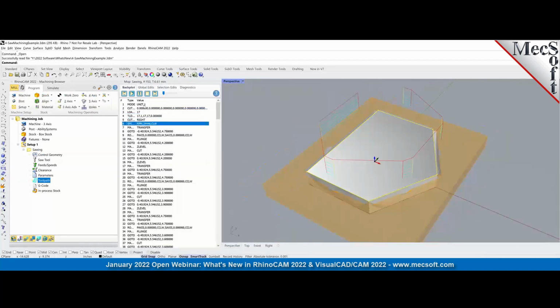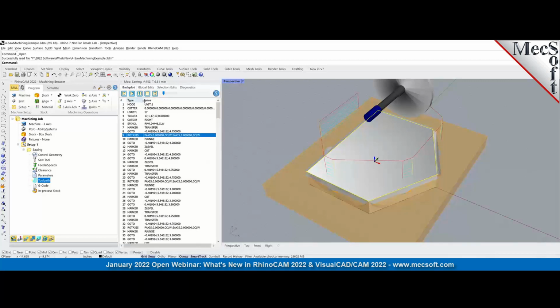This is our toolpath viewer. As it comes in here, you see a rotate axis, which is basically rotating the tool. We are just rotating the tool at that point, so it orients itself parallel to that line, and then it machines that, and then it goes up.